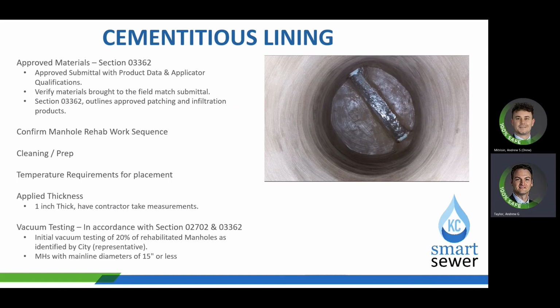During the application, have the contractor give you some thickness measurements as they work their way down and apply the cementitious lining to make sure that they are applying that at 1 inch thickness. That's important as well.